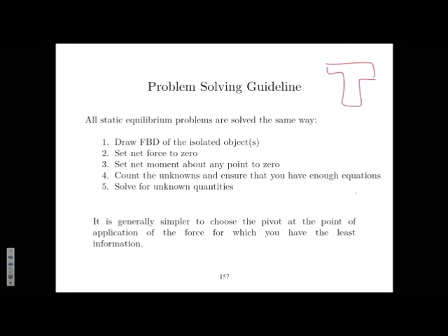Okay, you have this structure, and you have a point over here. Maybe there's a hinge joint over here. Let's call this point A, and I have a force along x direction, force along y direction. Let me draw the coordinate system. A pin joint can support reactions along both x and y directions, so I have forces over there, and then somebody is pulling here with a force of F.